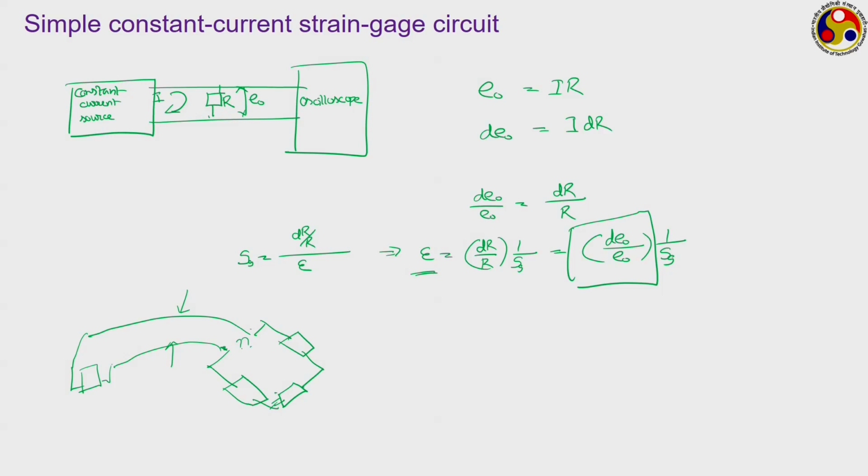So, this kind of error needs to be avoided. These are often referred to as lead wire errors. However, we can avoid them by using wires of very low resistance, or the more logical approach, we always try to keep the length of these wires short, so that the corresponding losses are minimum.